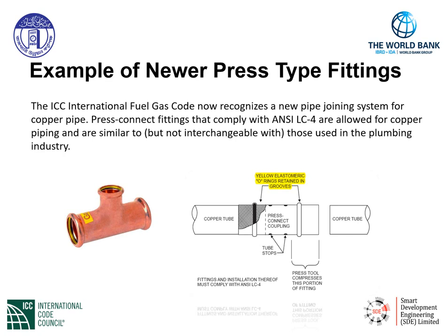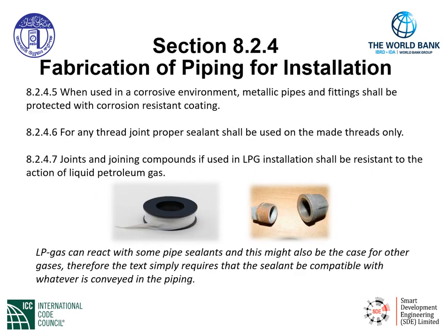When this force is applied, the end result is a gas-tight fitting. So again, the press tool compresses the portion of the fitting around the O-ring that's integrated and manufactured into the fitting. Fabrication is integrated here.